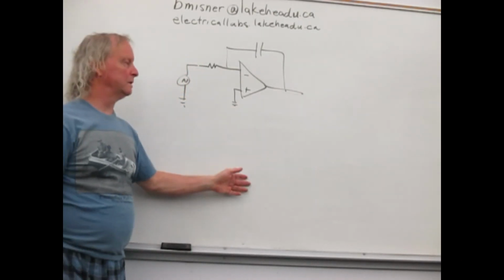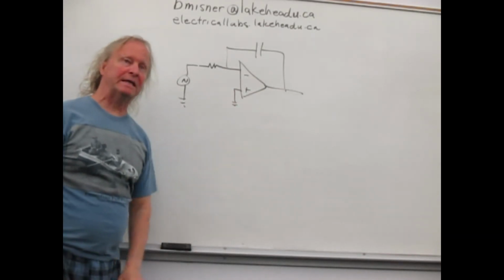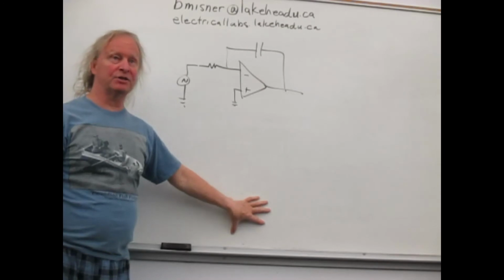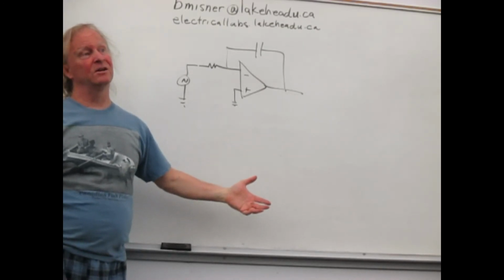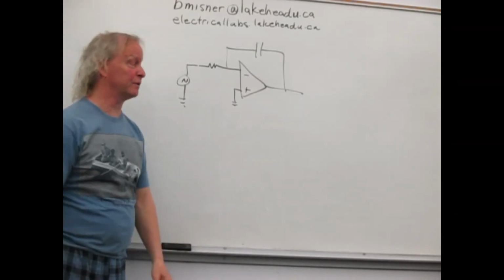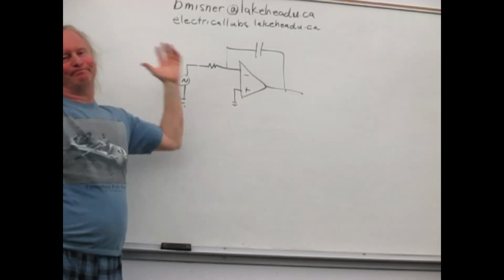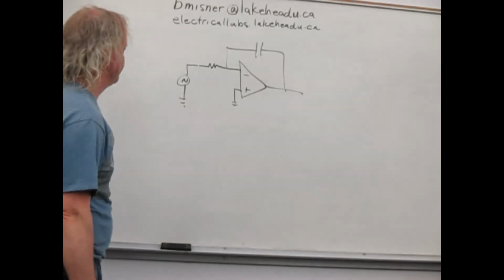Okay, and then one other thing I should mention, again, we're using the inverting input of this. So when I said that the derivative of the sine wave is cosine, when you see it in the demonstration, it's actually going to be minus cosine because it's an inverted circuit. Again, if you had the non-inverting circuitry, it becomes way more elaborate and way more difficult to deal with.